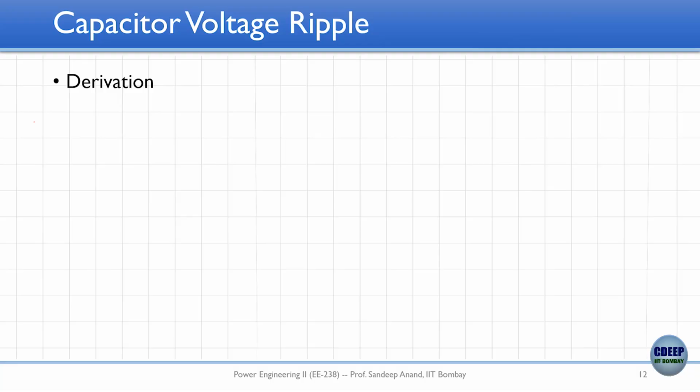So he is saying if your source is a square wave, then all the currents and voltages in the rest of the circuit should also be square waves, no? If I am calling this circuit linear, then he is saying, look, if your voltage source is a square wave, the rest of the things should also be square waves. Forget about the buck converter, he is saying this circuit: if you say this circuit is linear, then if the source is a square wave, every point should have a square wave.